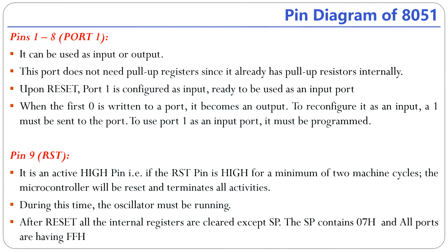Because it has to check whether the signal you are giving to the 8051 microcontroller is at least 2 machine cycles in period. That's why the oscillator must be running, and after reset every internal register is cleared except the stack pointer and these ports. This is the status of the processor after reset input.